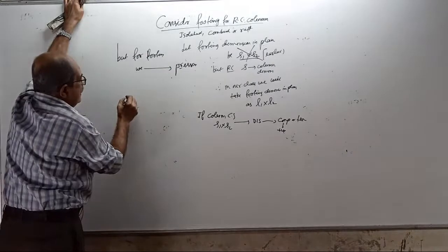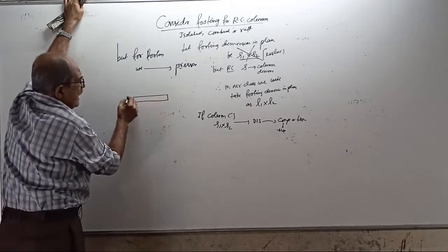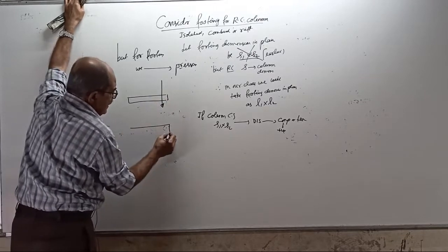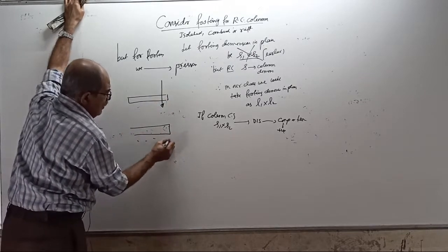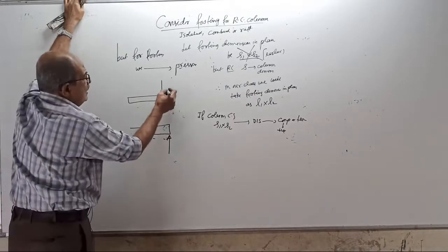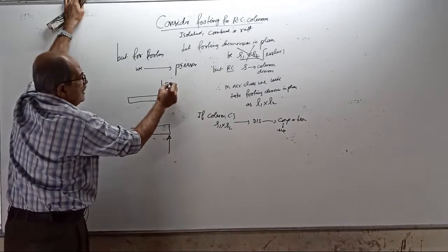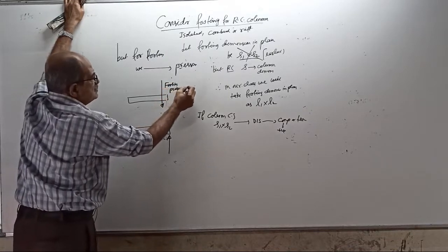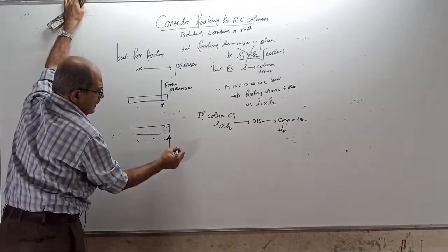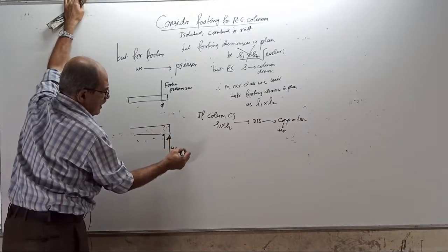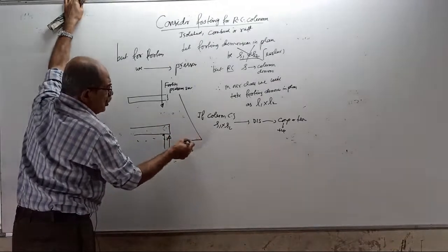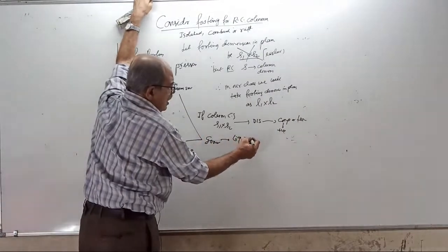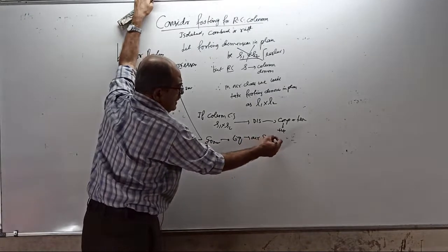Therefore, remember, if the footing slab presses the soil down, then from the soil there will be upward pressure. You write here, this is footing pressing soil. This is upward pressure. Upward pressure, this is good. This is equivalent to our compression in strength of materials.